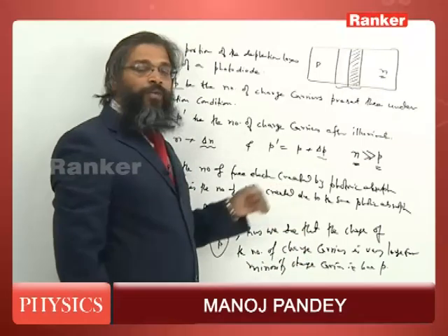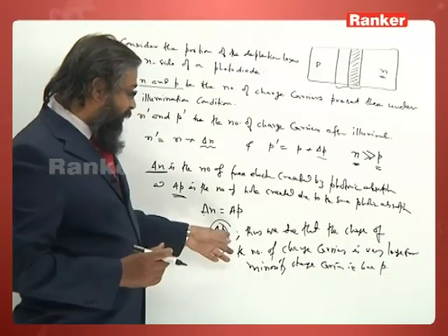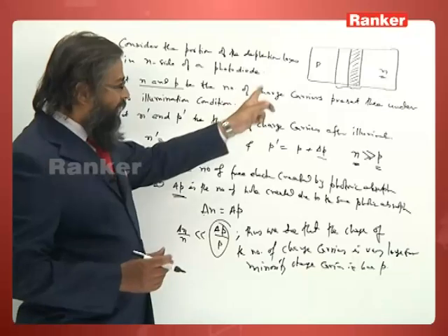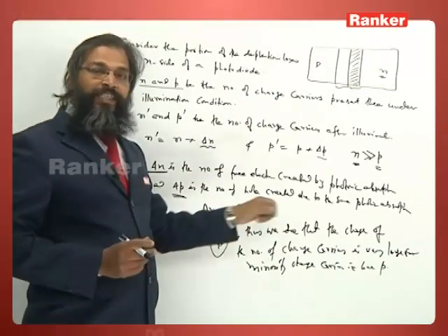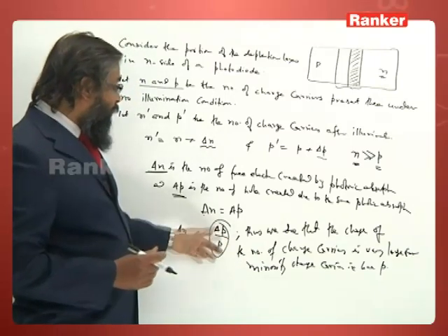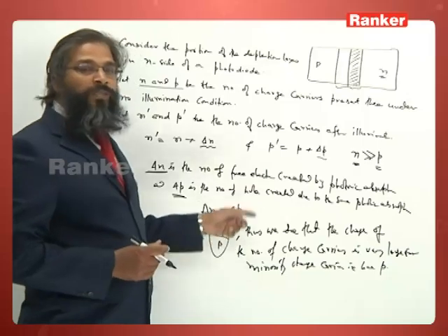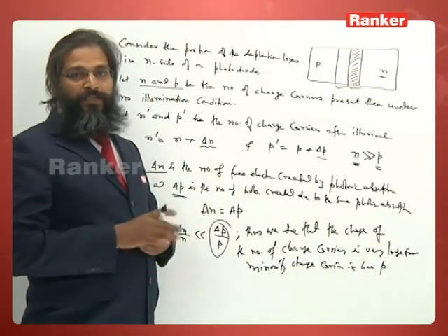Now that is what we discussed in the previous article, why it should be reverse biased. So during reverse bias, the current conduction is due to the minority charge carriers, where a small change can be easily noticed. So the photodiodes are always reverse connected.